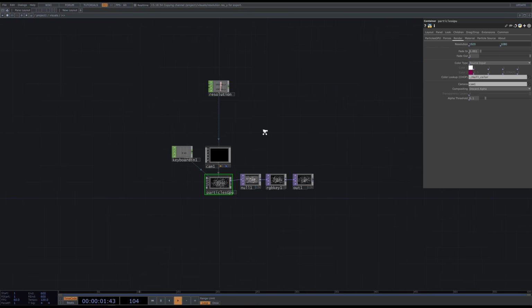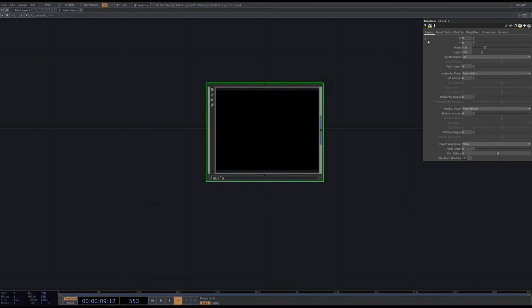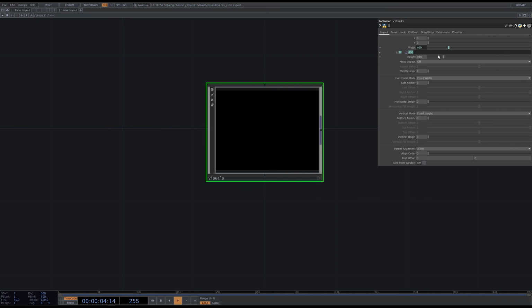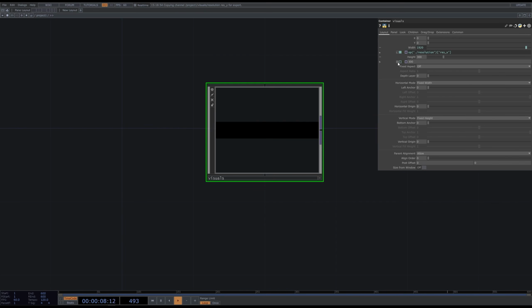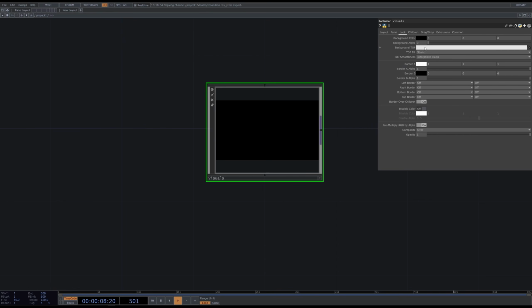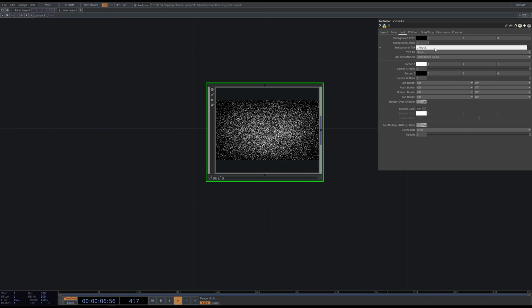Next, let's zoom out and set the same resolution in the container. To set the resolution that we defined inside this container, we need to type the following script. / means that the operator under the name resolution is located inside the component. Repeat for the height. In the Look tab, refer to the name of the operator inside the component you want to display.